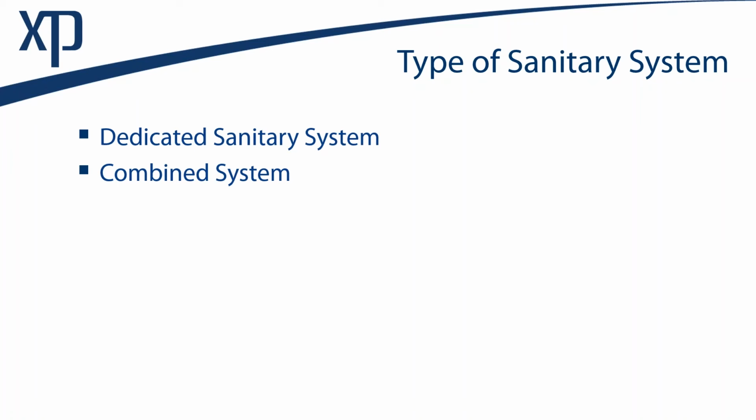The reason I wanted to segregate the discussion of just preparing data for sanitary systems is because of the sensitivity that dedicated sanitary systems have to rain-derived inflow and infiltration, more so than a combined system where we have a wide variety of flows entering the system.